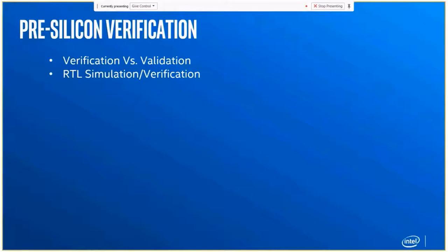On the other hand, it's really slow, right? So it's really going to look at clocks, look at individual bits, bytes. You trigger this one pin that's coming up, going down at that level, right? So you can imagine if you simply want to send one packet that needs to traverse through the whole device and come back, simulating the whole thing in RTL may take days, months, and maybe booting an operating system may take years or something, right? So that's not the purpose of RTL verification.